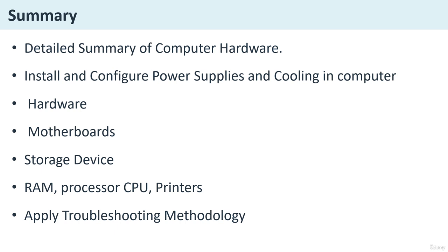Now, I will explain the cooling system types in depth so that you will understand it clearly. First of all, air cooling enhancements. There are heat pipes, which are metal tubes filled with liquid that transfer heat efficiently. In dual tower coolers, larger heat sinks with multiple fans provide extreme cooling. And now, downdraft coolers blow air directly onto the motherboard, helping VRM cooling.